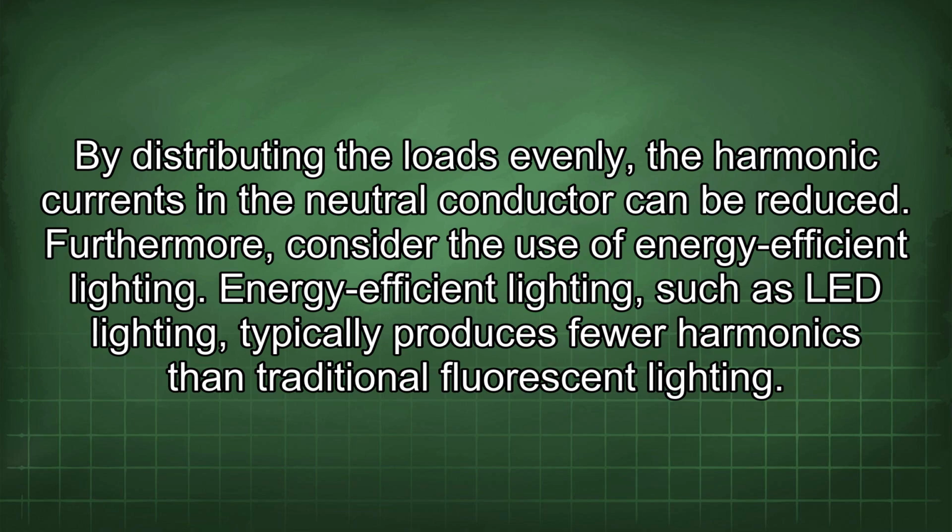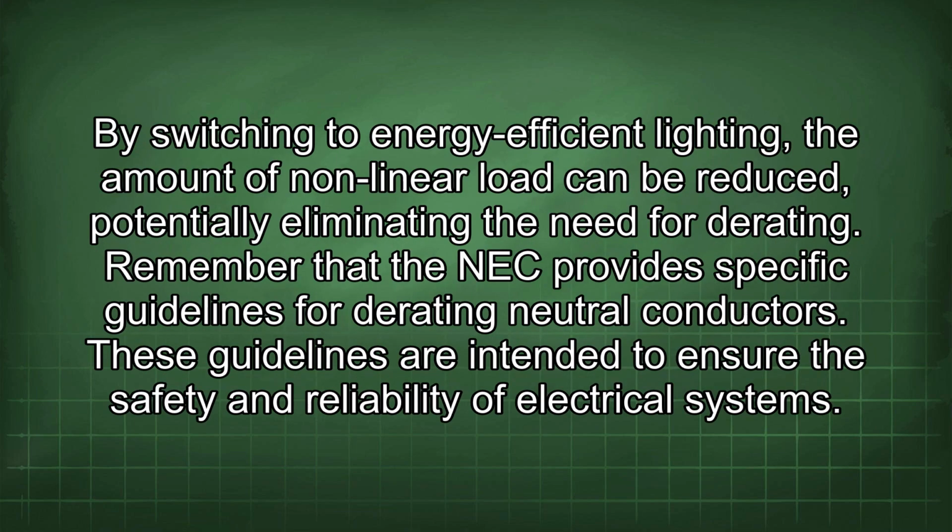Furthermore, consider the use of energy-efficient lighting. Energy-efficient lighting, such as LED lighting, typically produces fewer harmonics than traditional fluorescent lighting. By switching to energy-efficient lighting, the amount of nonlinear load can be reduced, potentially eliminating the need for derating.